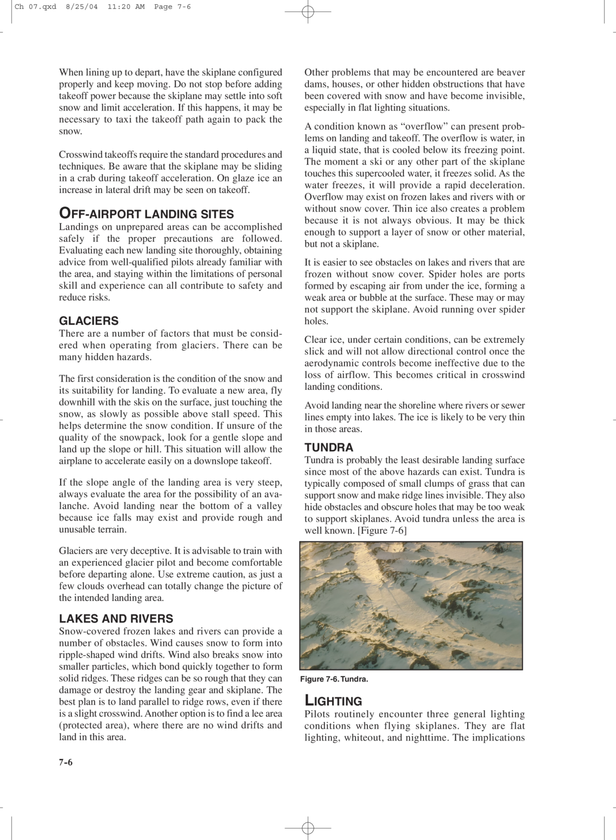Crosswind takeoffs require the standard procedures and techniques. Be aware that the skiplane may be sliding in a crab during takeoff acceleration. On glaze ice, an increase in lateral drift may be seen on takeoff.